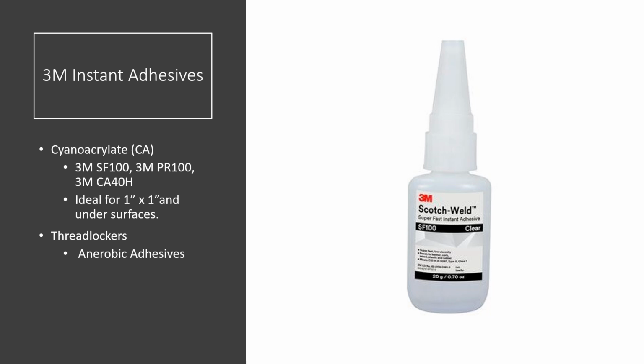Thread lockers, 3M also has thread lockers. These are adhesives basically applied to threaded fasteners to help provide a tight lock and seal and help prevent loosening due to stress loads, vibration, and shock. Now, there are different thread locker types. Some are permanent and some are removable.